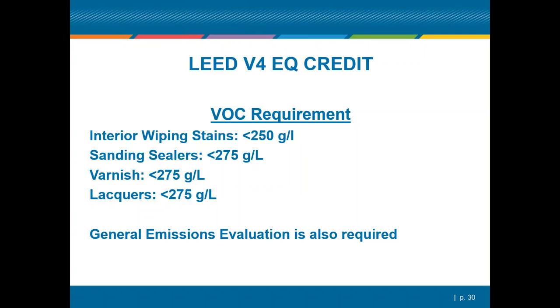I was involved in a situation here in Nashville just a couple of weeks ago on exactly the same circumstance. And in doing the evaluation, it looked as though the best option for this particular project was to stain and varnish off-site and then bring those components on-site and install. So keep those two things in mind whenever you're working through this, that we may need to actually do applications off-site or be very, very careful in the amount of product that we put on-site under that 10% offshoot that we have available there.